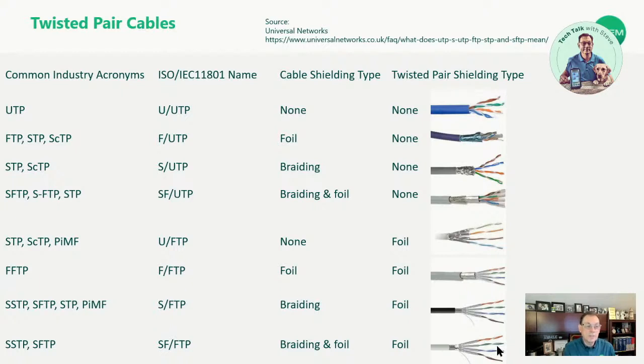The reason I wanted to show you these various types of shielded cables is that when we're talking about shield integrity, what we're really looking at is not just that our shield is continuous from end to end, but that the properties of the shield need to be the same from end to end whenever possible to mitigate any issues. Mixing different shielding types in the same cable plant can sometimes actually inhibit our noise mitigation. So we want to make sure that, where at all possible, these types of shielded cabling are compatible. Sometimes that's not always possible when we look at patch cords versus the installed cabling. Sometimes you can't always match that up.